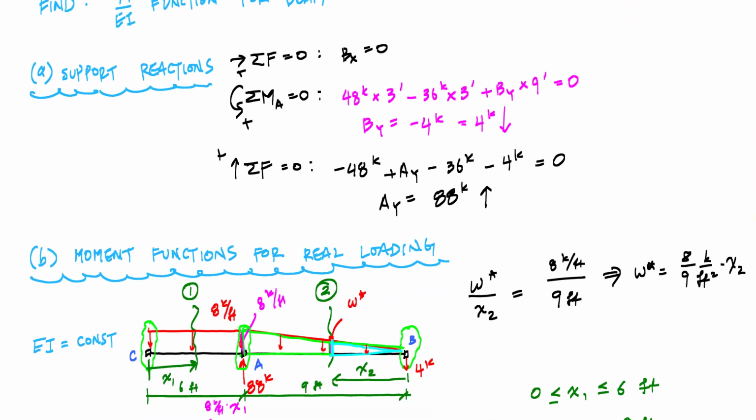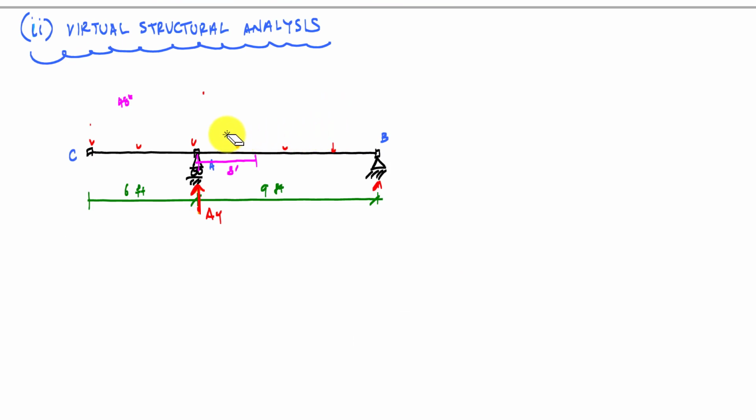And so if I go down, ooh, it's like a new page. Here, I'll call this part two. This will be my virtual structural analysis. This time, I'm only bringing the geometry with me. So on this overhang beam, I'm going to apply a virtual moment with a magnitude of 1, a unit virtual moment, at C right here. And I'm going to guess a direction, so I'm going to guess counterclockwise. This will have a virtual moment capital MV equal to 1 kip-foot. And here is my virtual structure. This capital MV is my virtual load, my unit virtual moment.